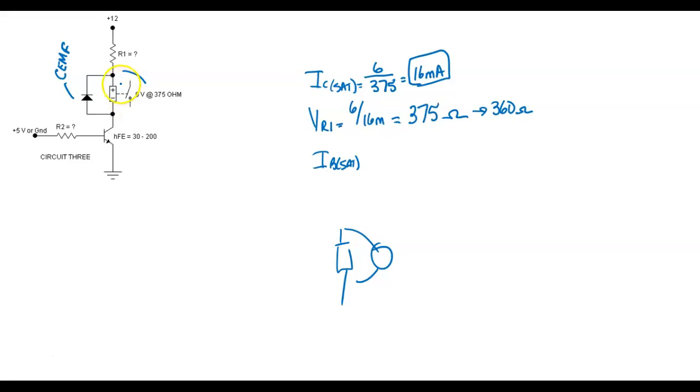Well, this is the true load, but the problem is I'm putting 12 volts across a 6-volt relay. What would happen? The relay is going to burn up because it would be trying to produce four times the power. Y'all know power varies with the square, right?